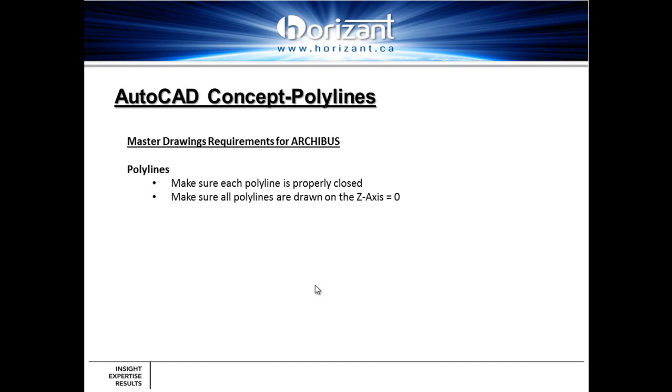If you leave it open, it does take a best guess to try to close it, but it's not always accurate. So you want to try to close as many of the polylines as possible as you draw them to ensure that it gets the right calculated area.